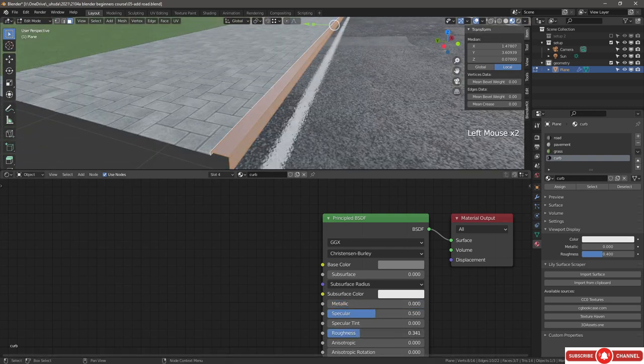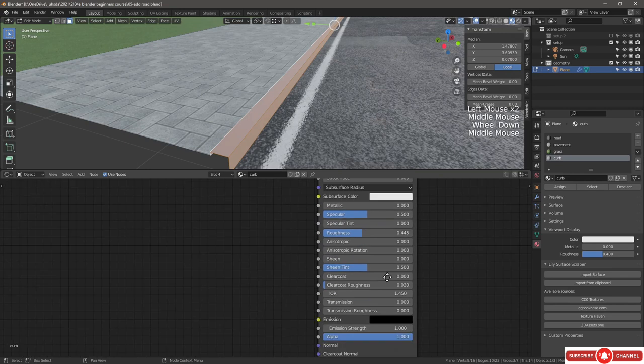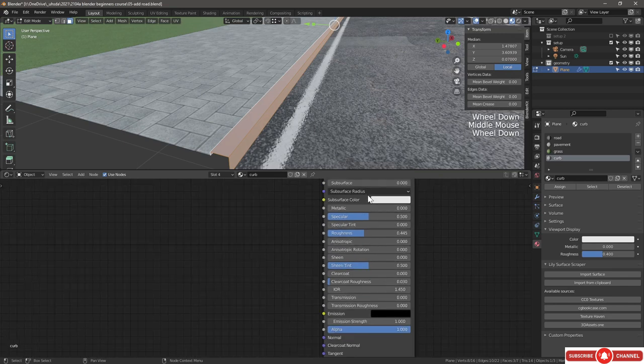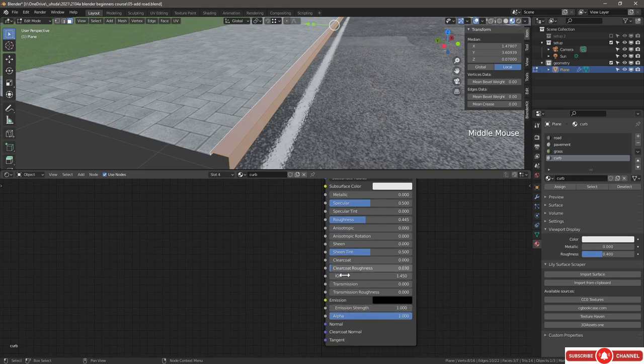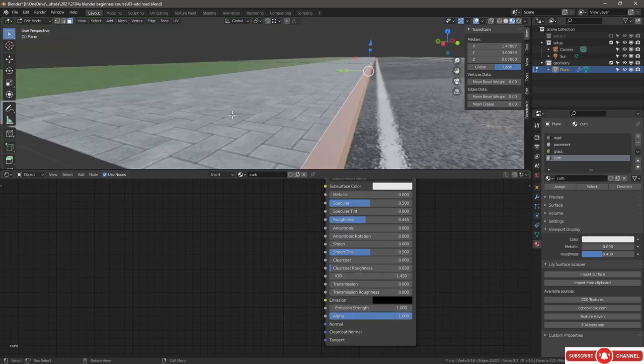Now if we change the roughness back to 0.5 and metallic to 0, now it's our default. We can also change the alpha strength here. And we have something that's called normals, which allows us to create these sort of fake bumps around, which interact nicely with light.